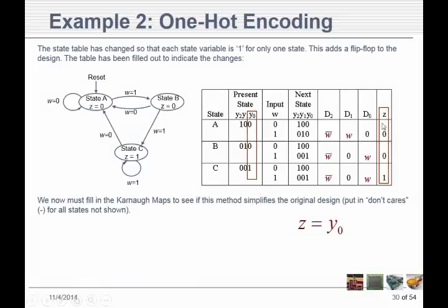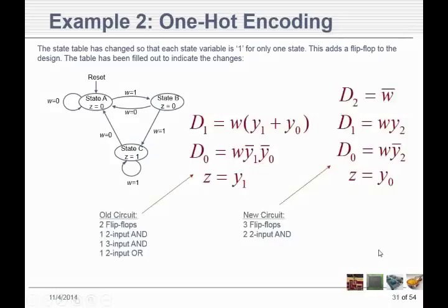Then I had to find something that looked at, remember, I can't say it enough, that the output is associated with the current state, but you can see that here in this diagram. The current state and the output are associated together. So when I look at this output of 0, 0, 1, I'm looking over here at the current state. Does anything pop out as being similar to that? And Y0 does. So I said our output was just the same as Y0.